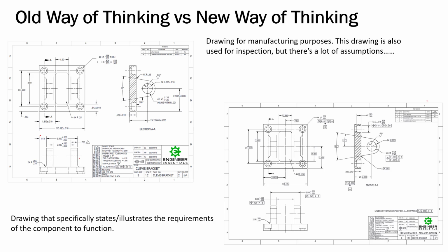The standard states that we should apply all the necessary geometric tolerances for guaranteeing that function. And like I said earlier, that's great, but what if you apply a profile tolerance and you don't have a CMM to measure it? Well, the standard states that with profile, within reason, you can use calipers or height gauges for checking. When it gets to really complex geometry, there are limitations there with traditional inspection equipment.